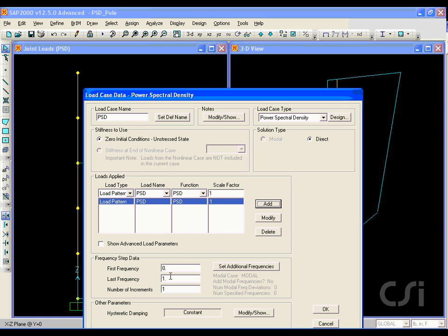One of the most critical steps in the data definition process is setting the frequency. This controls the shape of the output spectral density curves and thus ultimately the RMS values. We will start with a basic selection of whole number values of 0 through 5, but will need to add significantly more points, especially around the frequency of the model.